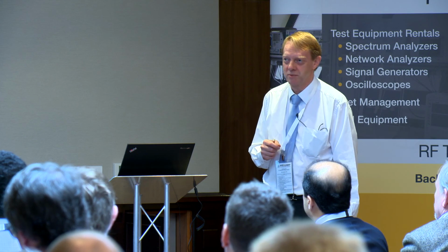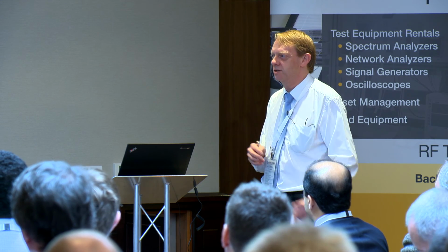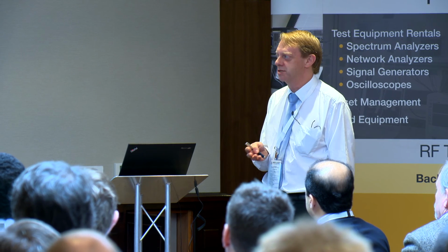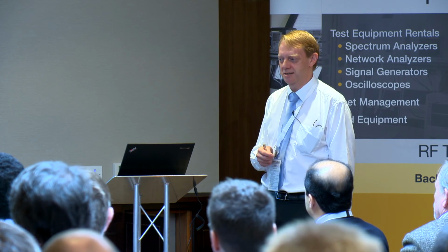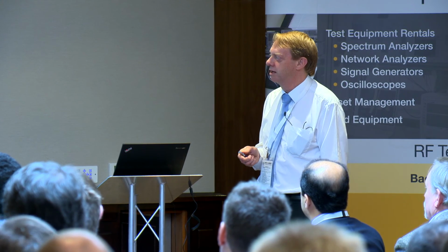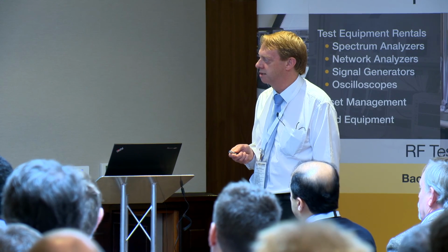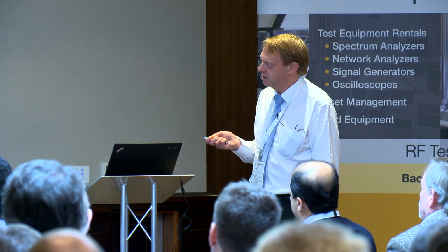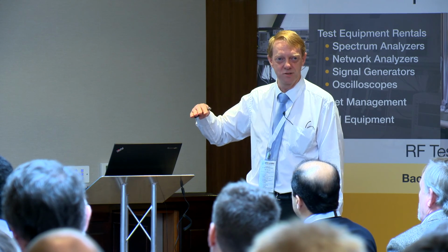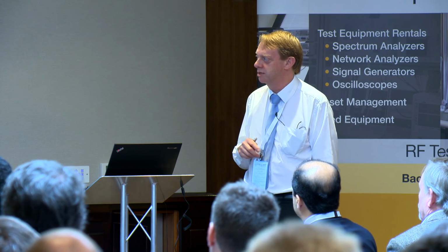I mean, it took quite a bit of finding out, why is it oscillating? Looking at the stability of each individual stage, everything's fine. It's because there's a feedback path, a positive feedback path that wasn't anticipated. It's certainly not in the circuit diagram to give you any hints. It involves quite a bit of work to find out which are the things causing the remaining coupling. And it turned out that taking that inductor there and placing it 90 degrees round on the circuit board was enough to create enough isolation between those two parts.